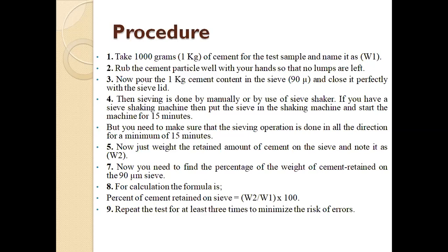During the sieving of the cement, it is necessary to do the sieving in all directions for a minimum of 15 minutes, either manually or by machine.